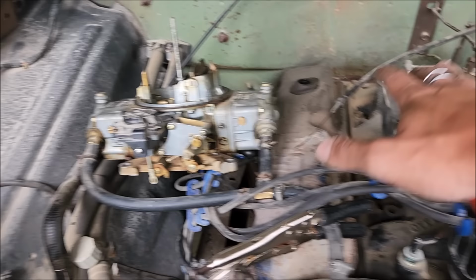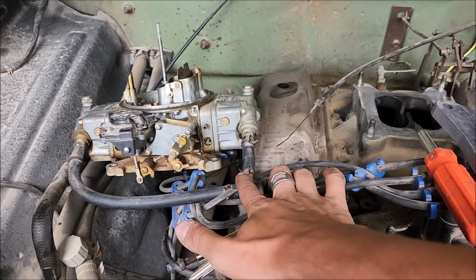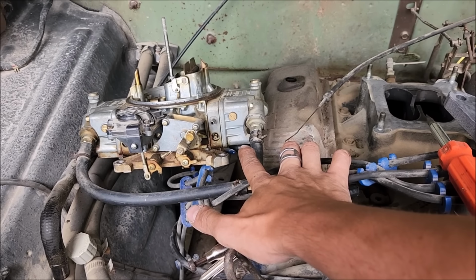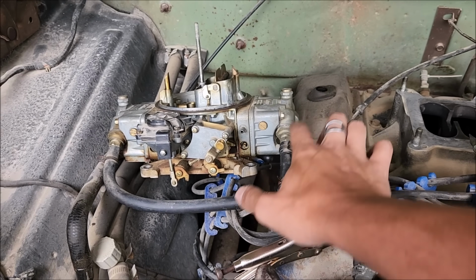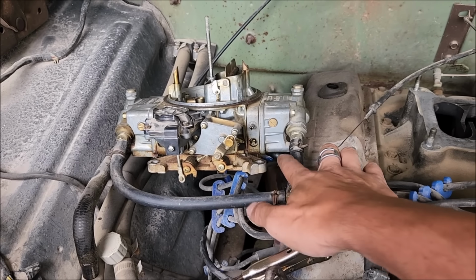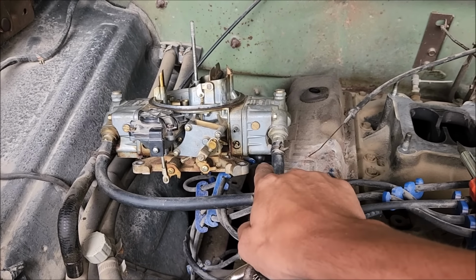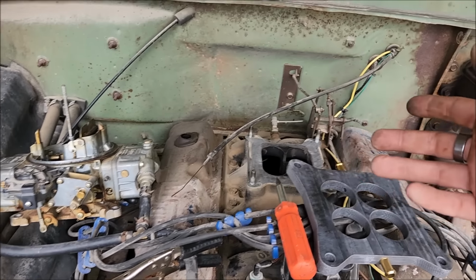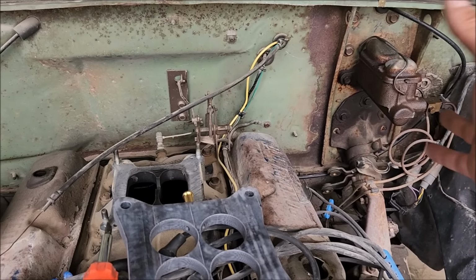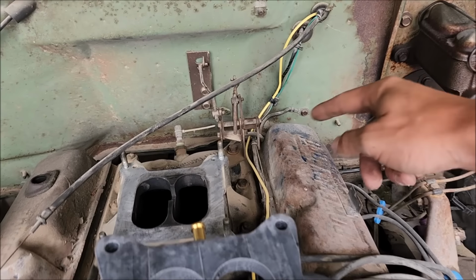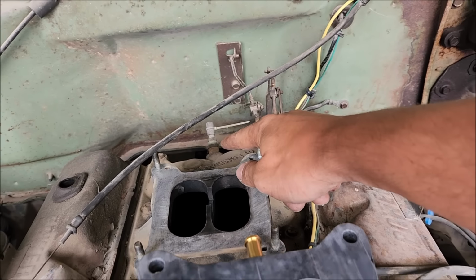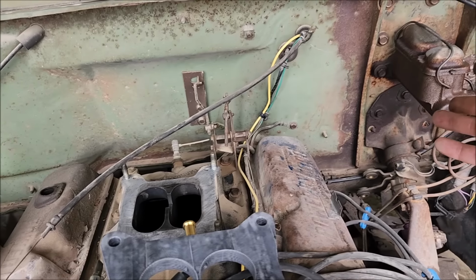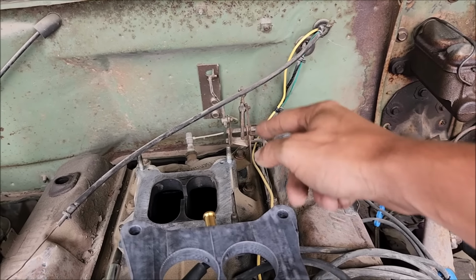And then for our Carb Cheater setup, we're going to want to go to the front primary throttle bore at a centralized location. In a lot of Holley carburetors, Edelbrock included, you already have this port. And then you might ask, well, what about your power brakes? This vehicle does not have that, but most intakes have a port on them for something such as power brakes, and that's generally where I'd hook that in.